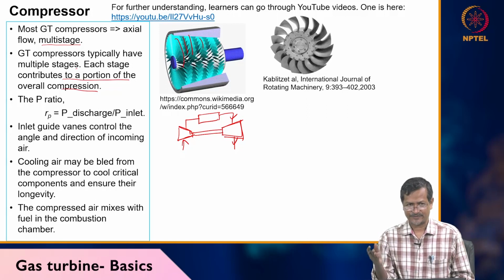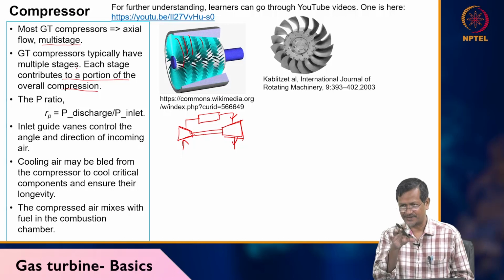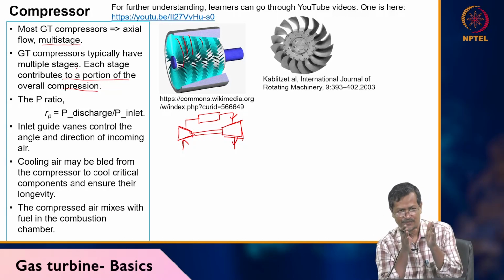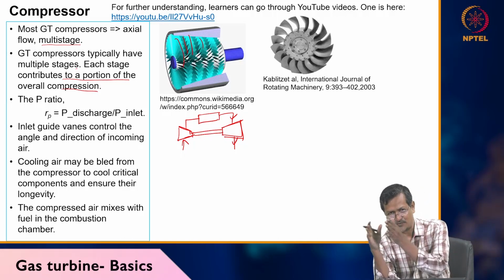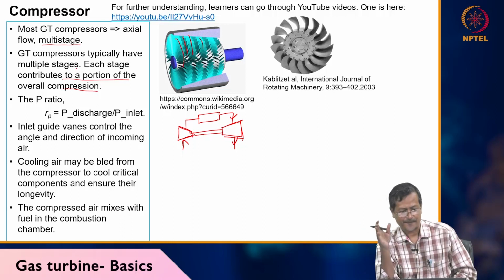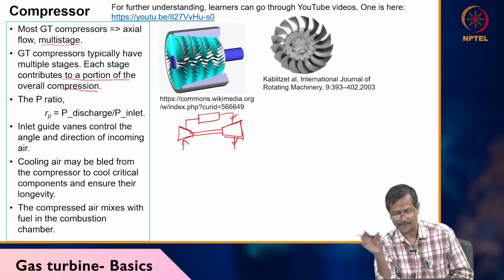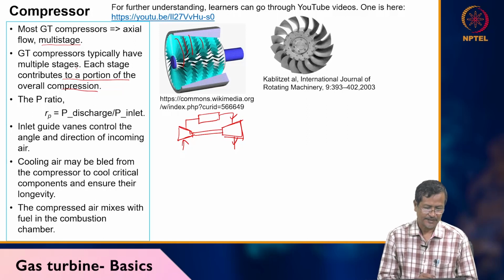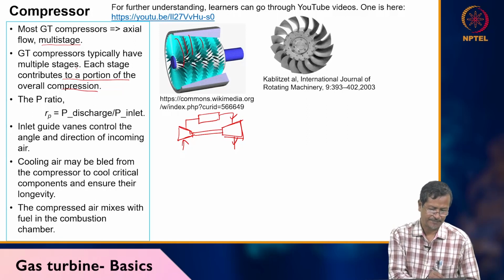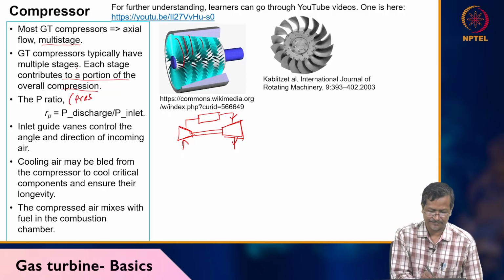In a pump system also you have seen that each stage develops a certain amount of pressure. In a pump we said head, but here we say pressure directly. So how much pressure are you increasing? One stage may be 1 bar, again 1 bar, 1 bar, so it multiplies. That way multiple stages help. Here I am writing P ratio, meaning pressure ratio.